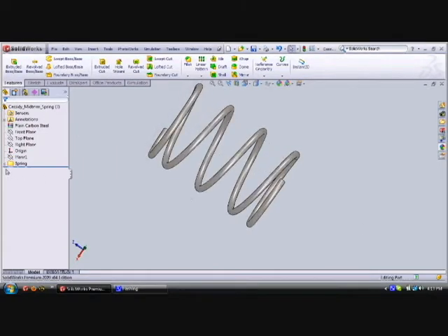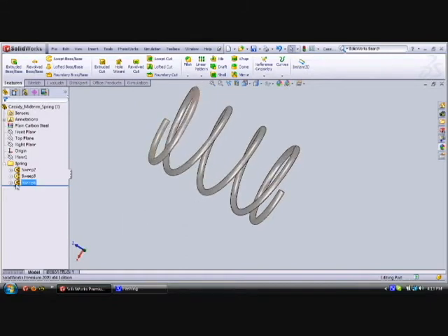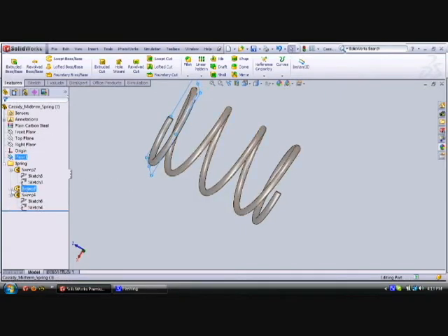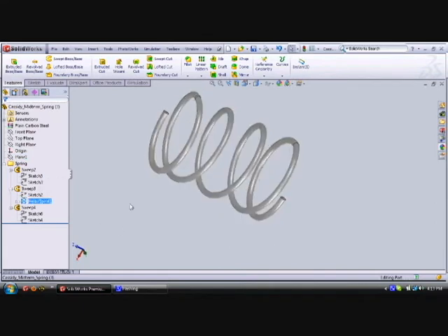This is the spring that goes around the cylinder. I made it using 3 sweeps. One sweep on the top plane, one sweep on a new plane that I made, and one sweep using a helix spiral of the bottom.